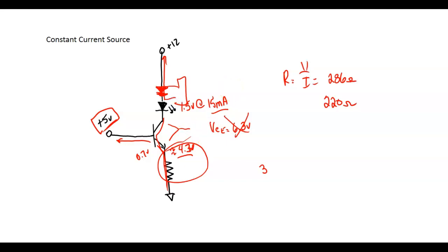You look at the specs of a NiCad battery, and it would tell you the charging current, or a lithium battery. Of course, you need to add a little more to that to automatically cut it off when it gets charged. There's a circuit monitoring the voltage output on the battery. When it charges up to the required voltage, it automatically cuts it off. Except for your phone, right? If you got your phone plugged in, the whole time it's plugged in, that little charger thing's up there.